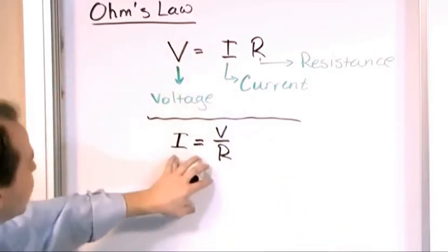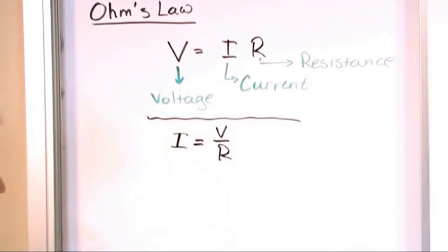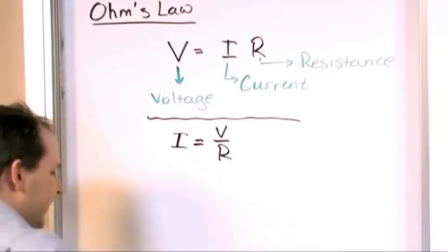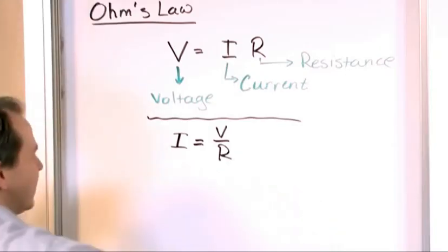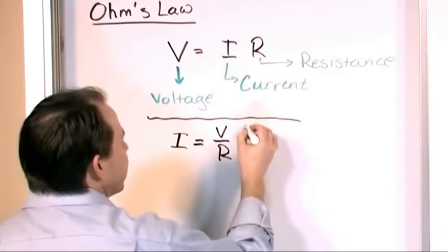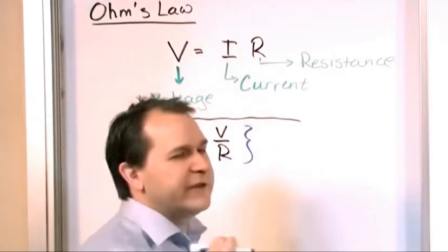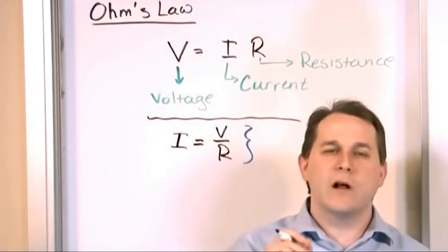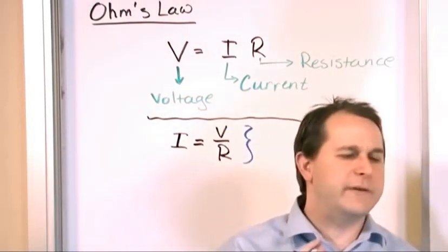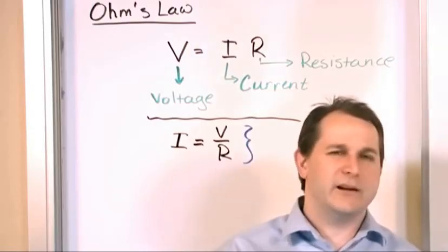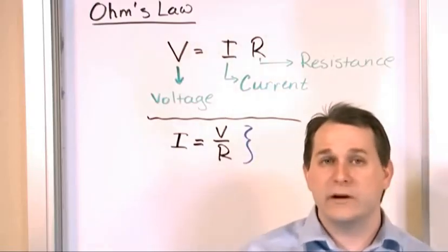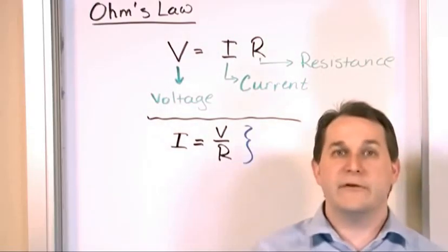All right, but this particular form is nice to talk about verbally because you can see very easily a few nice things about Ohm's law. Think about it. What we're saying is, if you have an object in your circuit, firstly, you've got to remember, Ohm's law applies to everything in the circuit, all the resistors. Later on, it'll be a slightly different story, but basically it's going to apply to capacitors and inductors and everything else going on.